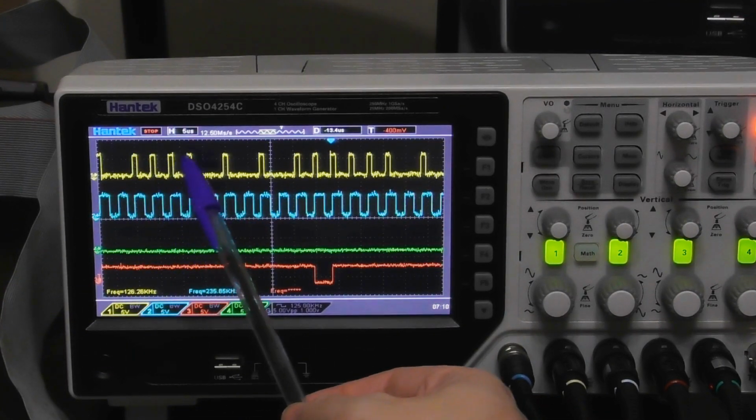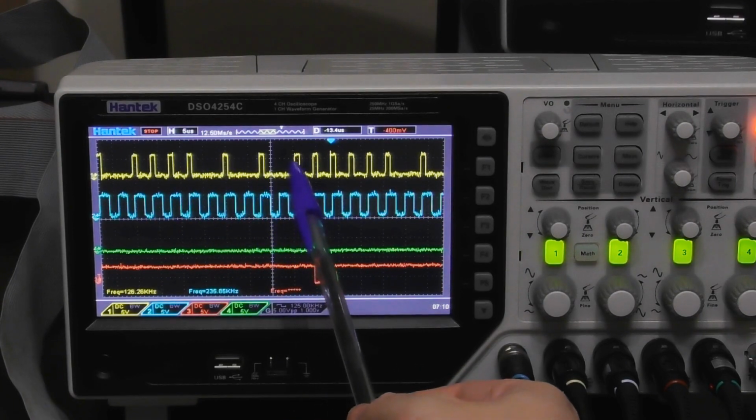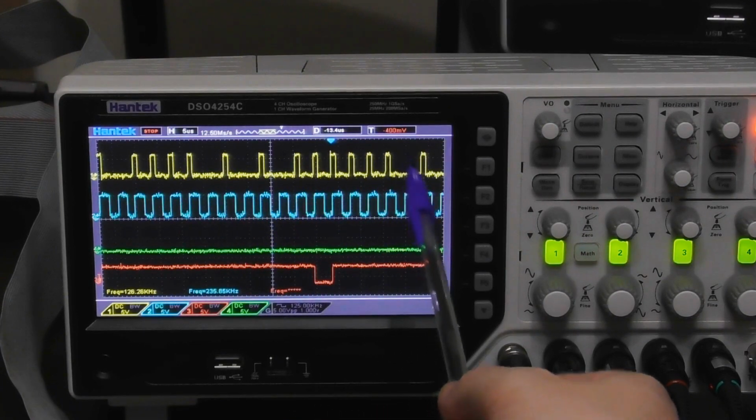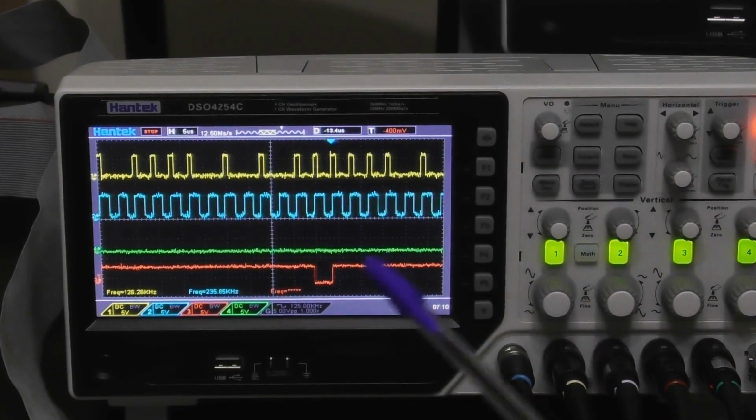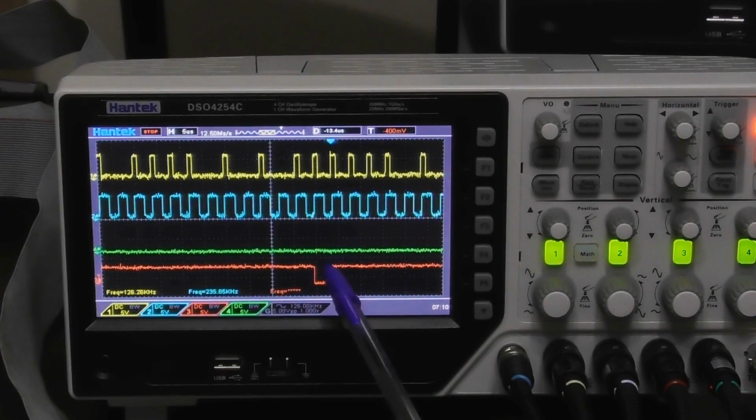So what have you got? 1, 1, 1, 1 is F, 1, 1, 1, 0 is E. So this was a sector ID byte, and that should mean that the signal coming low here, our little notch that we've created, should be enough for us to now trigger a counter. From this point on, we can then trigger some kind of latching to the CPU side of things once every 16 clock ticks after that point. So that's pretty good, because that reduces the frequency at which the CPU needs to poll things by a factor of 16, which is pretty nice.